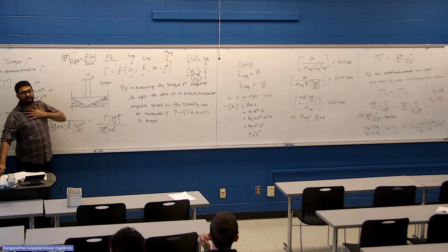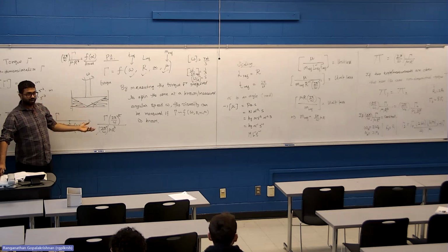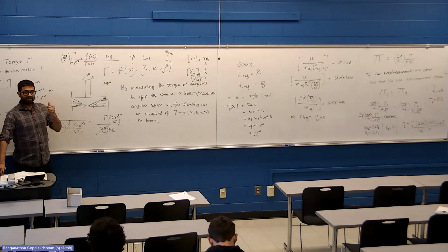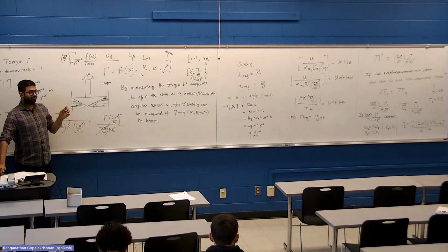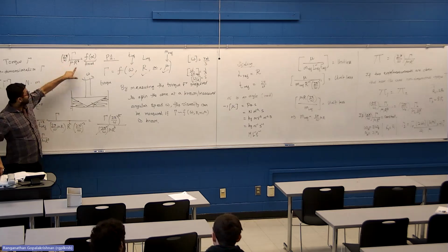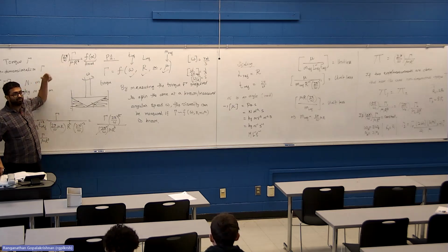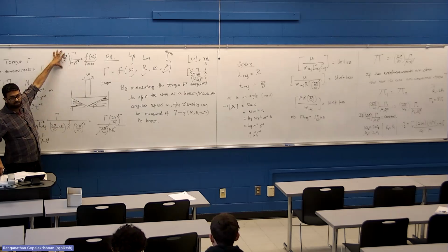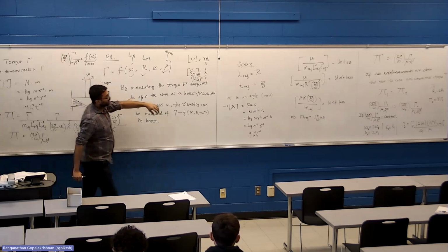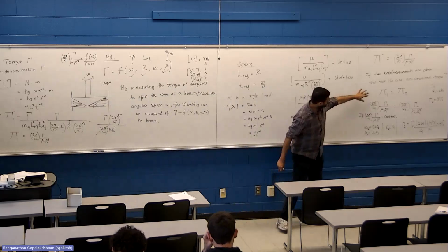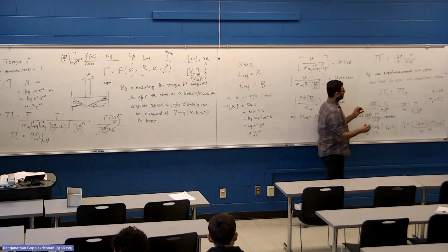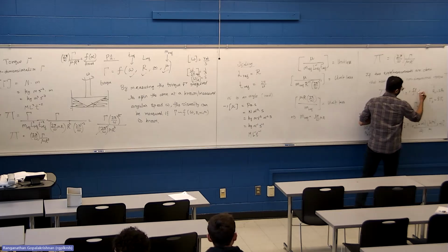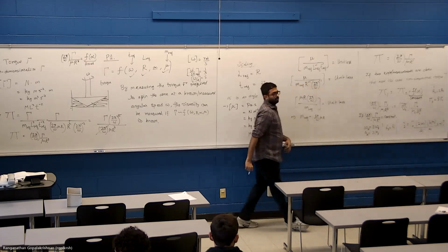So if I run an experiment with oil 1 and he runs an experiment with oil 2, we both will measure slightly different torques and slightly different rotation speeds because our fluids are different. But the idea is their combination should be equal. That is what pi is, their combination, the non-dimensional torque. So this is equal to f of alpha, which is nothing but a constant number.